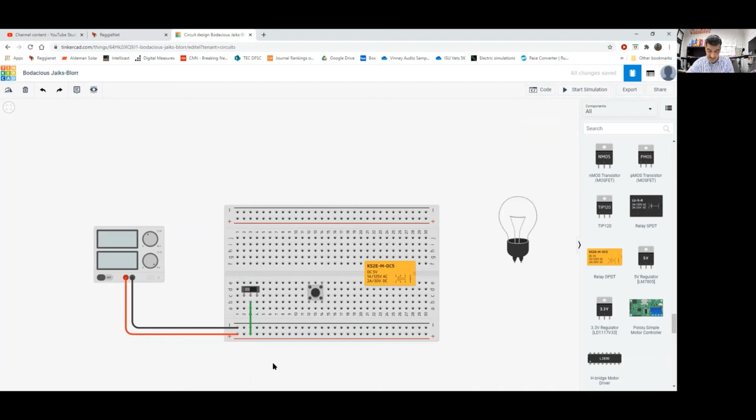I move to the right on that rung, and I see that I need a wire from the output of the stop slide switch to the input of the start push button. So the output is going to be right here. So I need a wire from right here to the start push button. That's right there. There's our second wire.